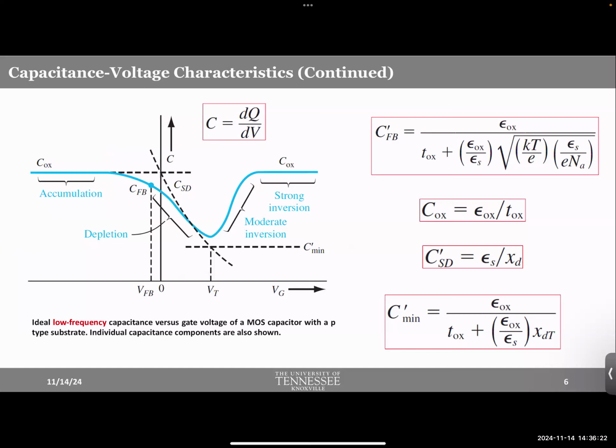The CV property, the capacitance voltage property of a MOSFET, which, by the way, we experimentally measure. So if you have a MOSFET device, or if you design a new MOSFET structure, you do two kinds of characterization at the minimum. You test current voltage property, which will be the topic of the next lecture, and you test capacitance voltage property, which is the topic of this particular lecture. Okay, just two characterizations will suffice.